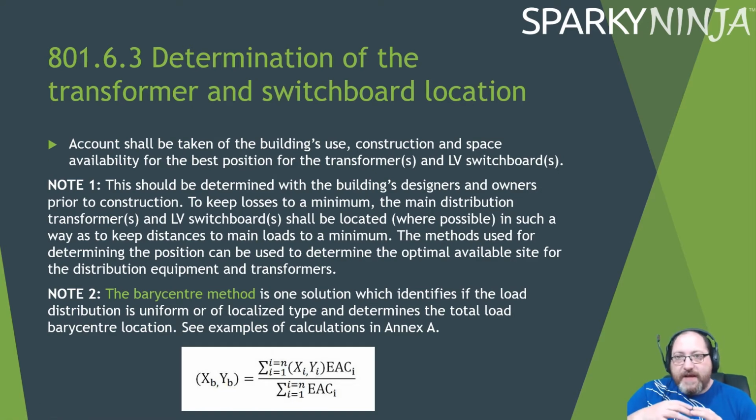We also have account taken of the building's use, construction and space available for the best position of the transformer and LV switchboards. So, couple of notes. It should be determined with the building's designer and owners prior to construction. So before they build it, it needs to be determined where the best place for distribution is. The barycenter method is one solution which identifies if the load distribution is uniform or a localized type and determines the total load barycenter location.